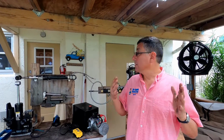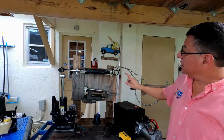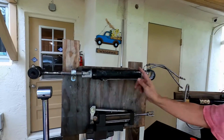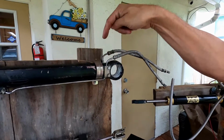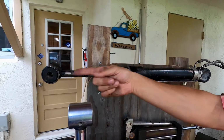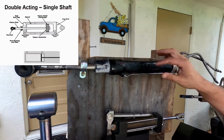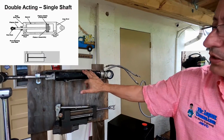Okay, guys, those are the main components of the hydraulic system. The last elements are the cylinders. We have a lot of cylinders, different types of cylinders, but the most common cylinders are cylinders like this. This is double port, one port for input, the other one here. This is double port, single shaft, exactly like the cylinder that we have on the screen right now.